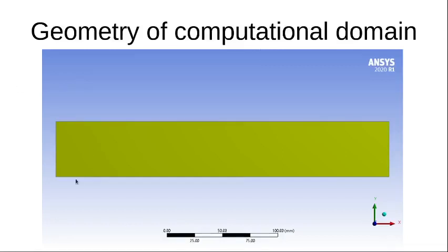So the boundaries of that would be, at the bottom I have the flat plate over which the flow is happening, and this is the leading edge of the flat plate at the left hand, which is x is equal to 0, and I have got a domain which is 30 centimeters long, so I have a plate which is 30 centimeters long, and in the vertical direction I have solved anywhere between 2.5 and 5 centimeters, so that the boundary layer thickness, of course, normally would be within a couple of centimeters at most, depending on what fluid and what Reynolds number that I am using. So I have used up to 5 centimeters here, and in some case, in the case of water, I have used up to 2.5 centimeters. Right? So that is the thing.